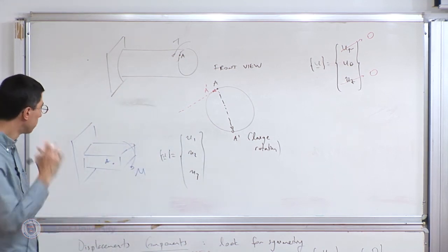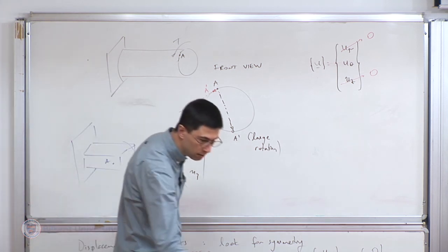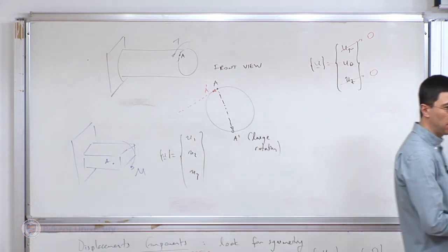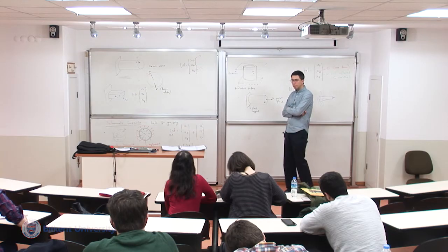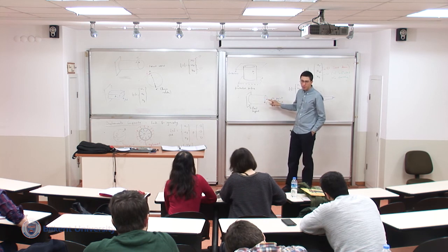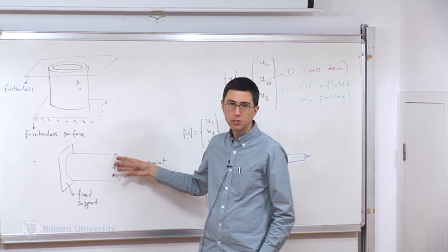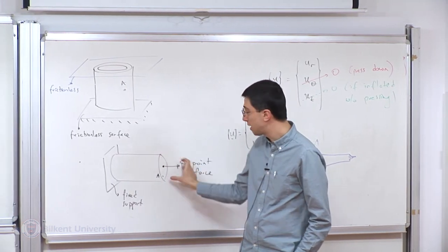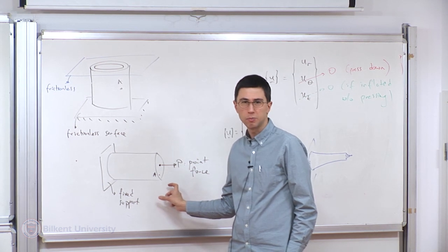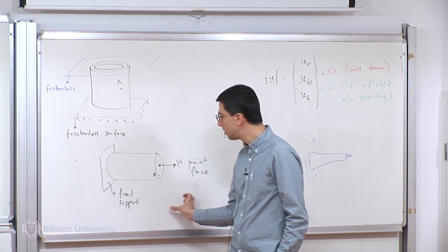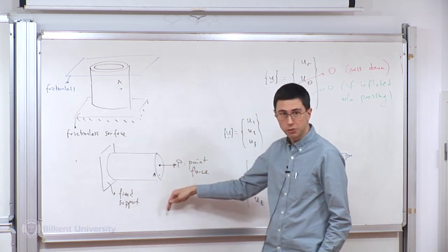So there being no symmetry, you would say that I have to proceed with a Cartesian coordinate system. There isn't much to do, right? So if we have such a problem, then we have to stick to our good old coordinate system. You should also be aware that you could take this problem, which has cylindrical geometric symmetry. But now if I apply a bending moment to it, the deformation itself does not have a symmetry. So if I try to bend it, there is going to be also motion in the vertical direction.